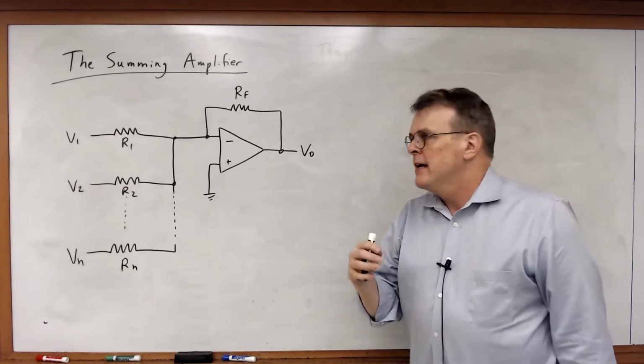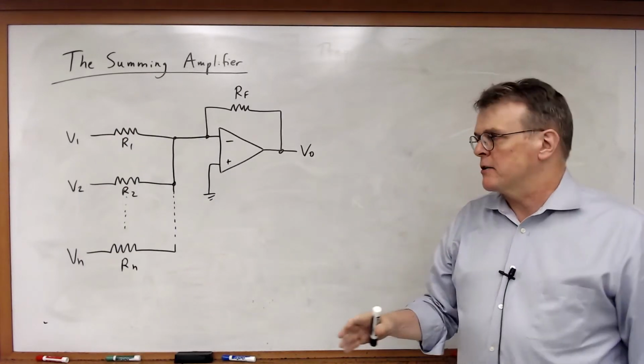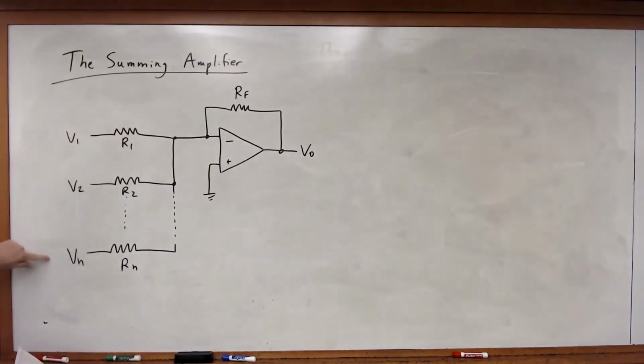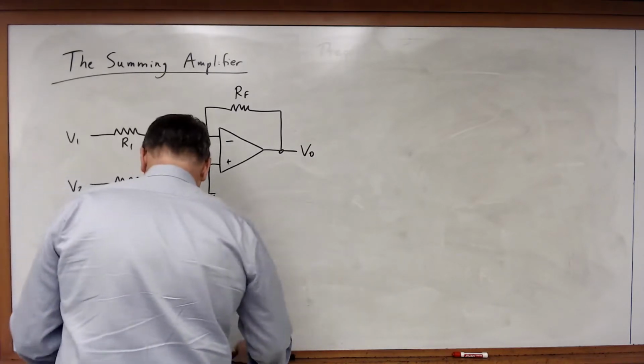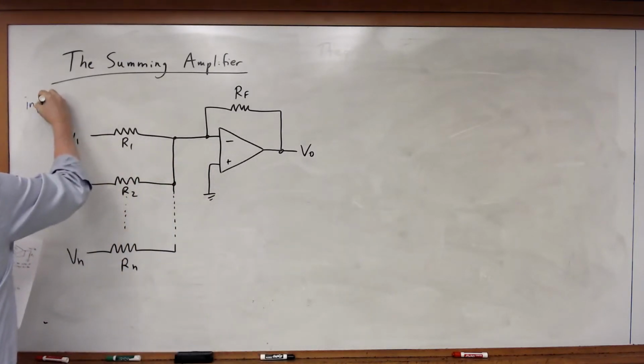Once again, this is a convention you will see in circuit schematics. When you simply see a voltage represented on one side, especially on the left side of the schematic, that usually represents a source that is generating these voltages, which is not shown. So there are input sources that are not drawn.